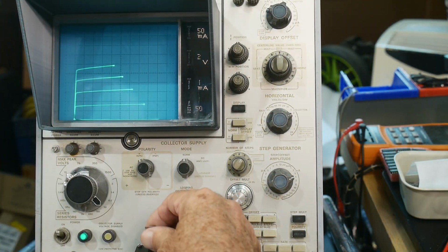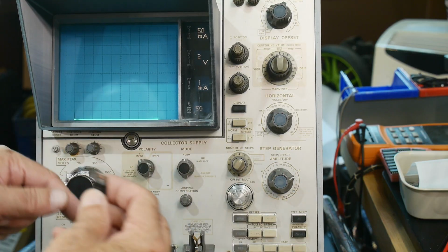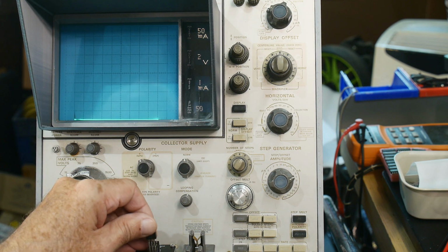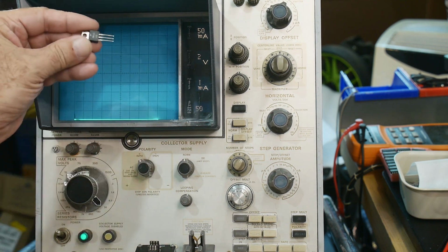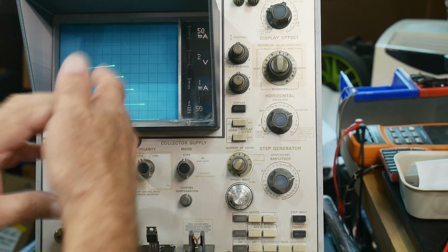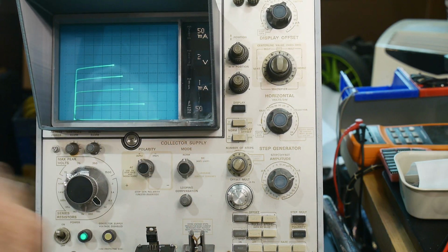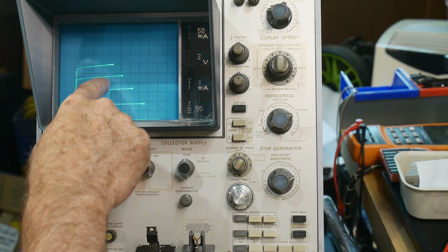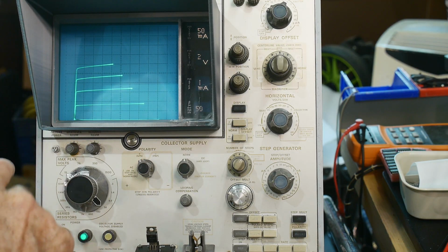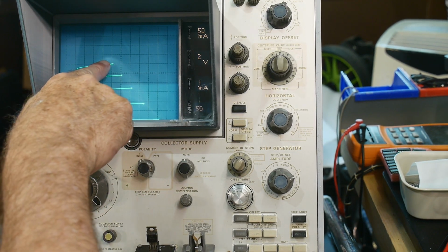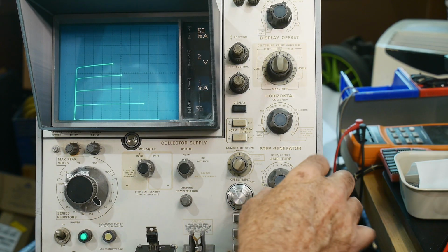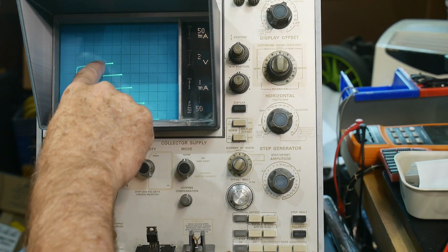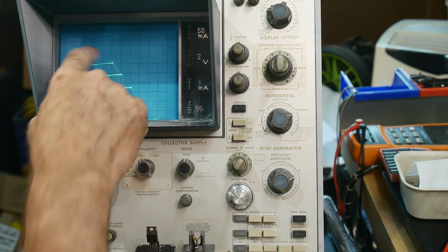So this transistor, like I showed before, the other transistor was a 2N2222. This is a 2N6121, and a 6121 is a big fat package, so I've set it up for more current. Now we're at 50 milliamps per division: 5, 10, 15, 20, 25. So 300 milliamps, this is 300 milliamps here. And we have our steps at 1 milliamp: 1 milliamp, 2 milliamps, 3 milliamps, 4 milliamps base current. These are the different base currents.